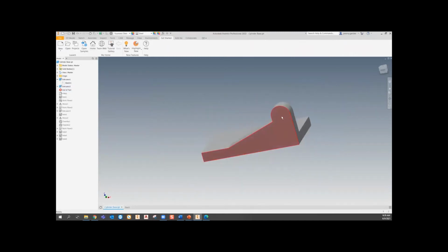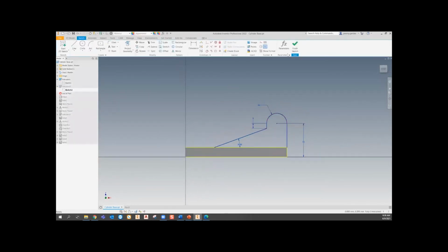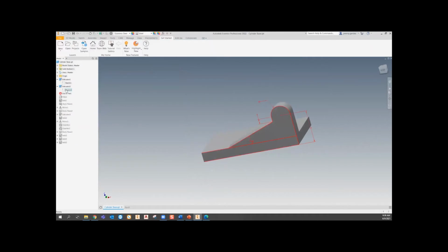So the next thing is they have this dog-eared part, I guess I can call it. And let's see how they made that. I can click either edit sketch to edit the sketch, or if I just want to see what the sketch was, if I click visibility, it turns the visibility of the sketch on. And so that has benefits. If I create a sketch and I do a feature with that sketch, the sketch is used up. So you can't use that sketch again unless you right click and either hit share sketch or visibility to be able to use that sketch again for another feature.